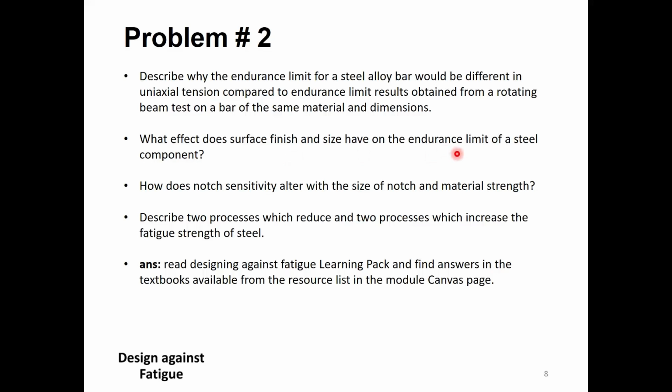So it affects the endurance limit, whether the specimen is a standard specimen or a larger or smaller specimen. And also based on the surface finish of the specimen, either it is smooth or just machined or forged, etc. So you need to find out what effect this surface finish has on the endurance limit.